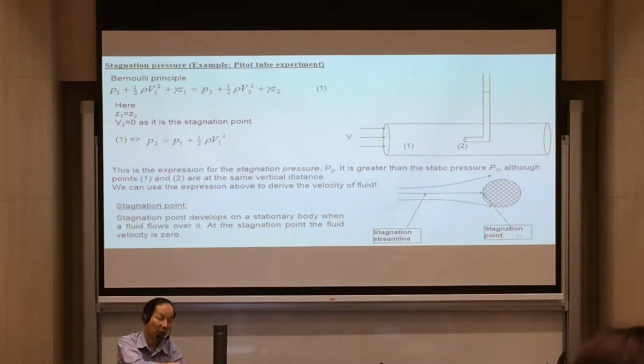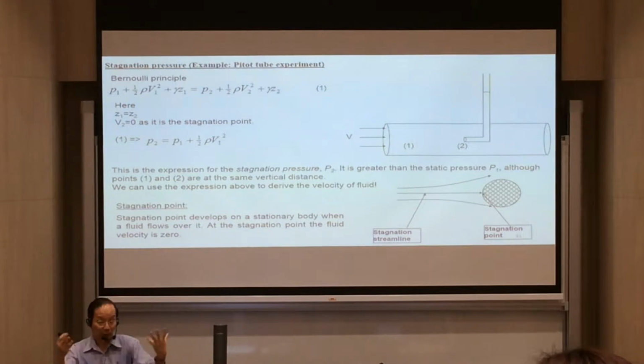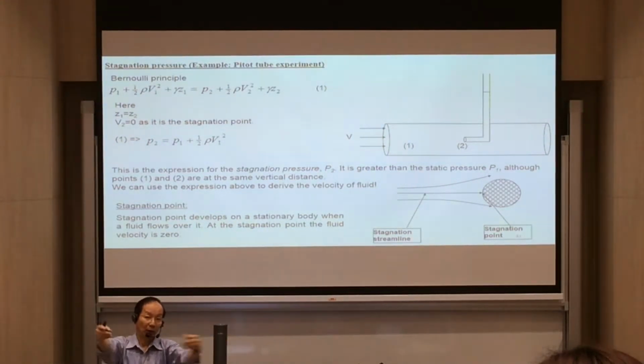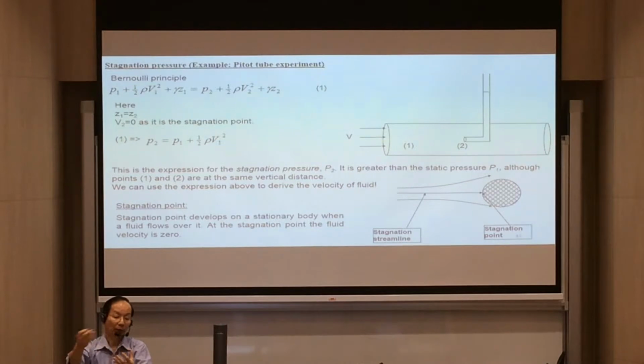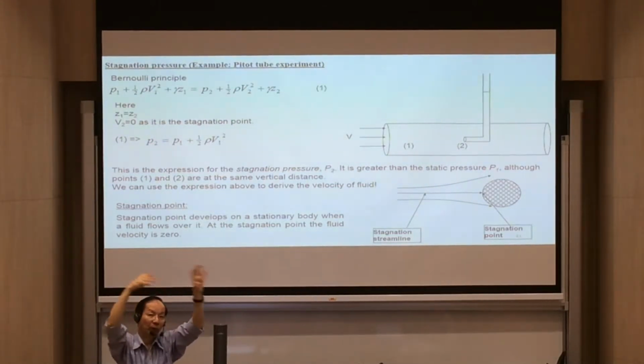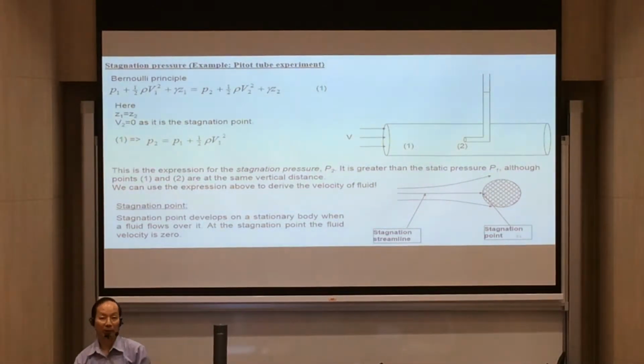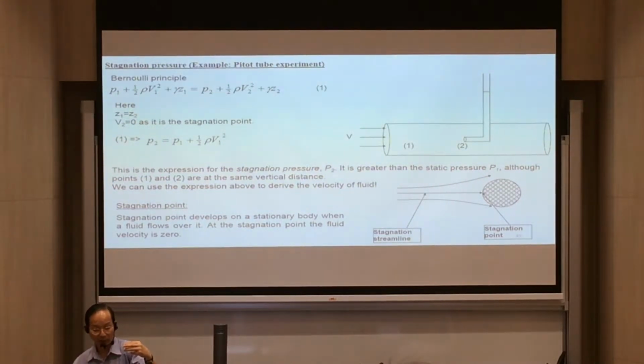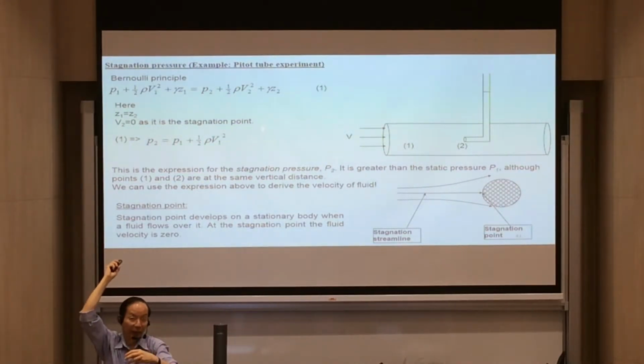What if you have a pump instead, in the building? For example, in your apartment, you open the tap and the water comes through. Usually the water is pumped through a header tank. But let's say you don't have a header tank, in a different case, and the water goes from a pump directly to your tap. The pump provides the pressure, it pumps the water to your tap. So in this case, this expression will be modified again.